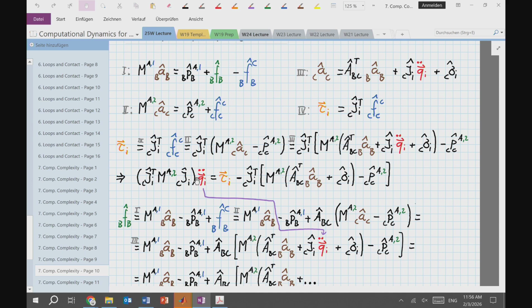This is something between 1 and 6 dimensions. Times some mass matrix equals the corresponding force quantities, which of course means the motor torques, which live in that same space of n motion primitives, and bias stuff that just depends on velocities. In this case it also depends on accelerations of the predecessor.